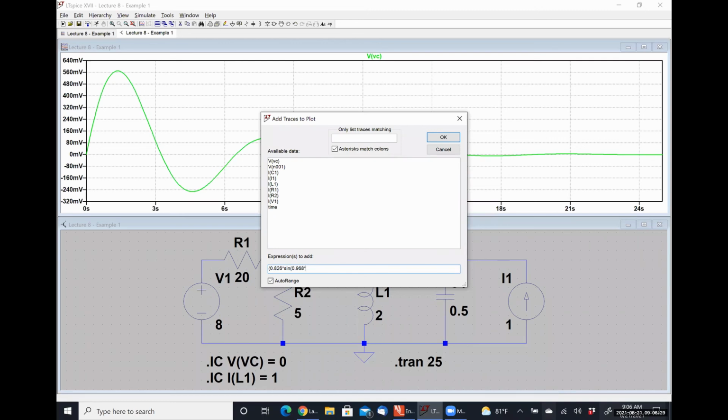If you don't do this, your answers are always going to look like they're wrong. LTspice does everything in degrees. Omega_d, by definition, is radians per second. So we need to convert it to degrees per second, so I'm going to multiply by 180 and divide by pi. If I do not do that, my analytical solution will not match the simulation.